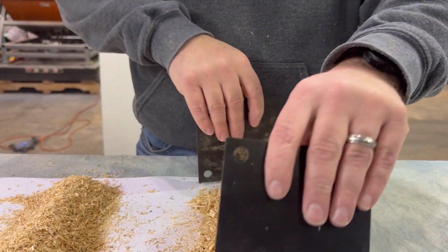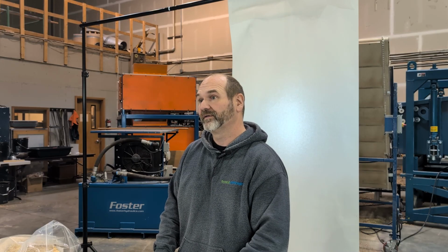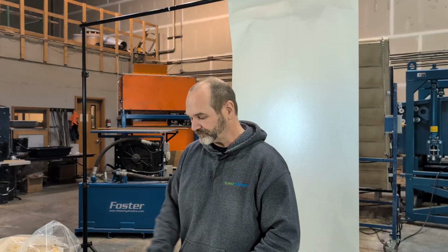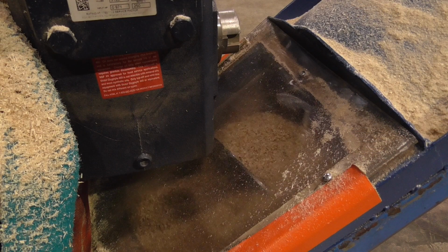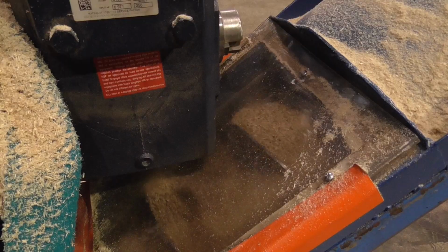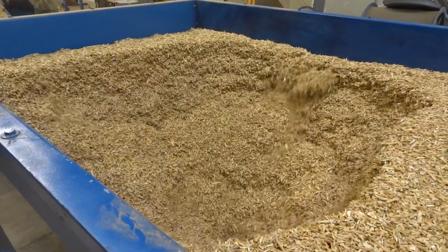So running high aspect ratio material can plug up your auger reactors. It can plug up some of your transition points at your different points in your material handling system, and it can plug up your feed hoppers. So your feed hoppers have to be designed specifically to be able to deal with these less flowable materials. Whereas conversely, I can take my high flowability, my low aspect ratio materials, and feed my downstream processes, not plug up my auger, not plug up my transition points at my conveyors, and not plug up my hoppers.